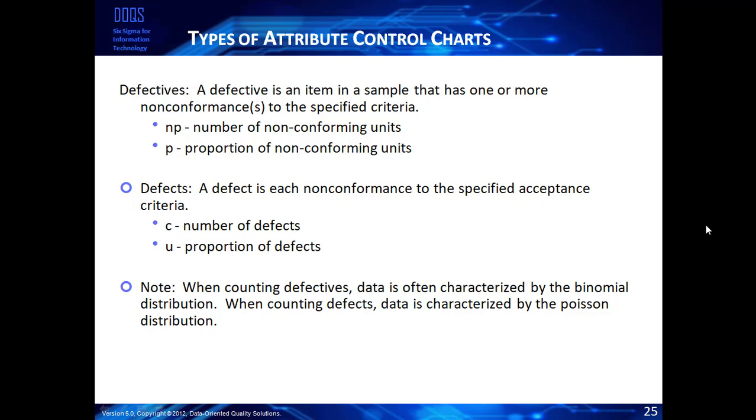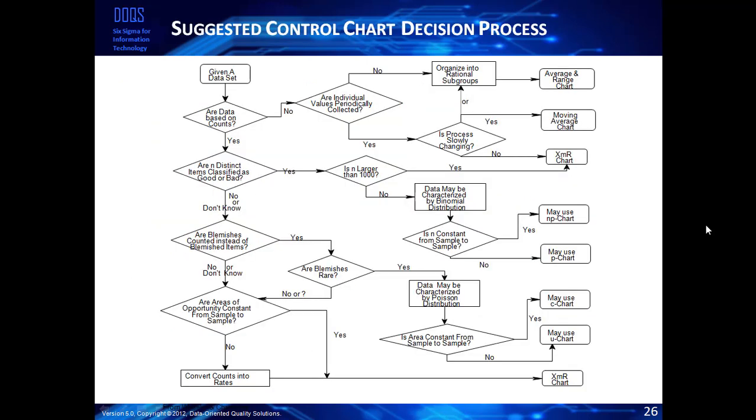So like I said, there are a family of control charts here. There are actually a dozen or more different kinds of control charts, but the vast majority of them will be the X bar R chart to measure a basic process, and then the P chart or the C chart to track defectives and defects. This is a basic control chart flow to help you decide which chart you're going to be using of all the different charts, the size of your sample size, as well as the type of data you're recording are basically the criteria for knowing which kind of chart you would be drawing.